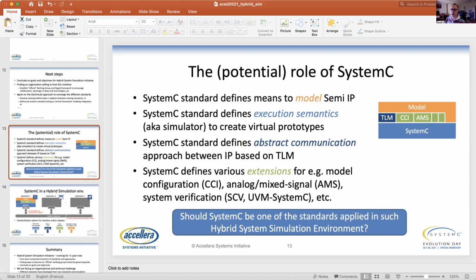As far as the SystemC world is concerned, it's the SystemC world. There are interfaces between components within SystemC, but as far as I'm aware, there's no real interface between a SystemC model and the outside world. The only way you could do that is to have the outside world, whatever it is, represented as a SystemC model, and then black magic could happen inside that thing. But from the SystemC perspective, that would then look like yet another SystemC model. There's no concept in SystemC of a foreign object and an API to a foreign object, as it were. There's no synchronization mechanism. There's no plug.